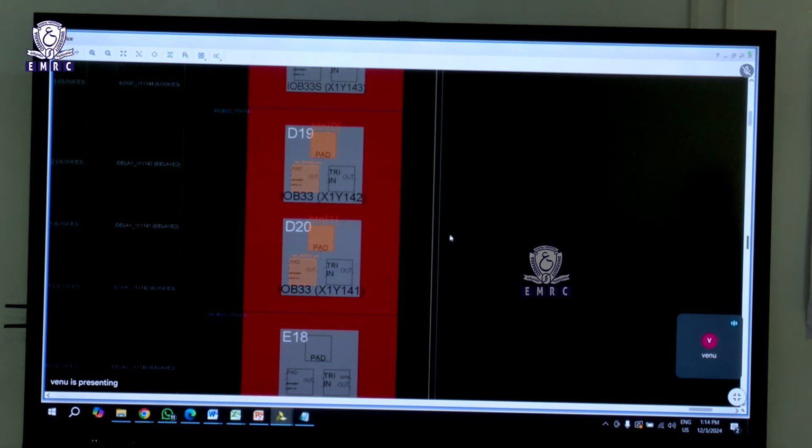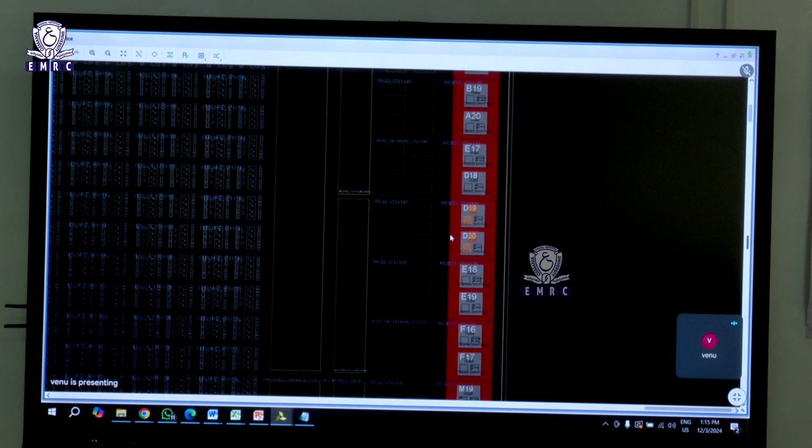So what is happening after I run the implementation is that my design is getting translated onto the device with placement and routing. PNR is happening. Placement and routing: it is placing where each cell and each net of my design needs to be, and at the same time it is telling how I route this design, where I place it, to get the best optimal result, right?